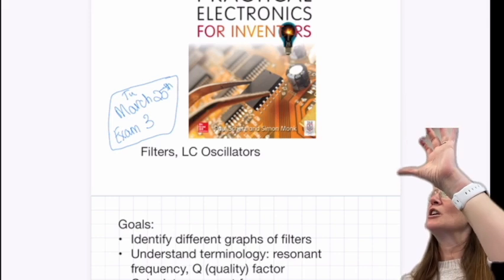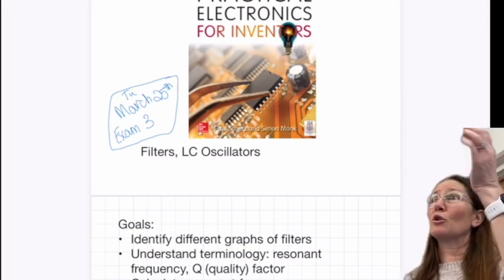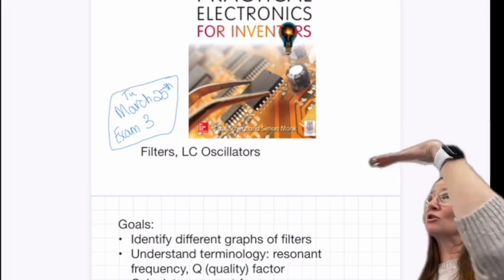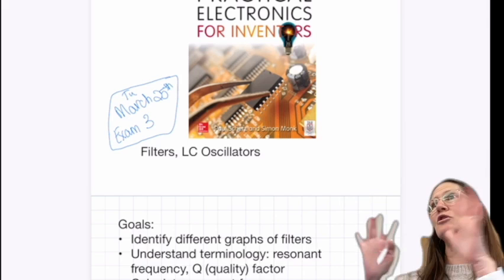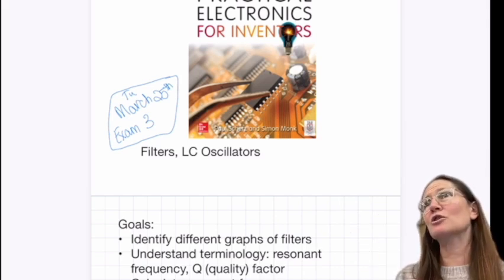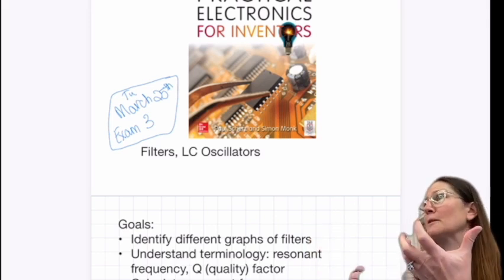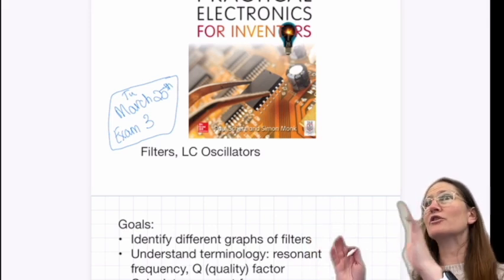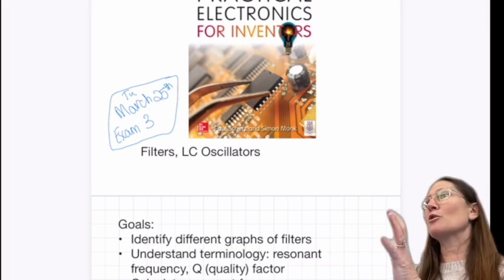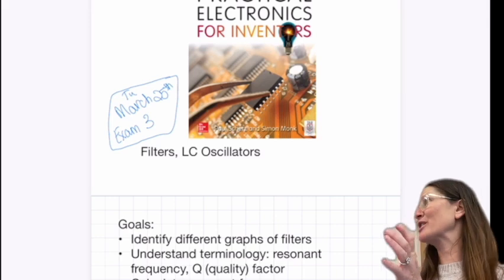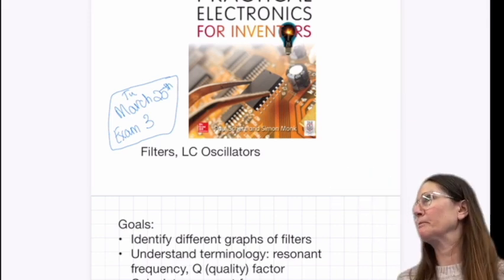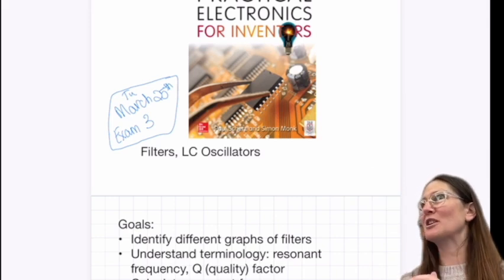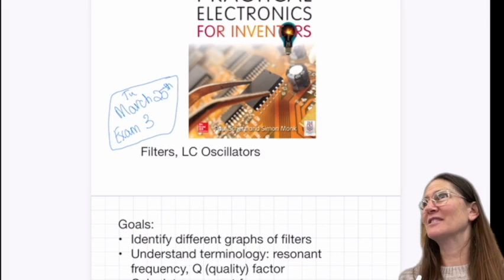For any more than one, you change the capacitor over to 1/CS and the inductor over to LS, and then use the same techniques you've already learned to get an expression of V out over V in. From there, that transfer function you can manipulate with algebra to get it into that standard form that you can then plot for a Bode plot. Any questions on any of those steps or concepts?